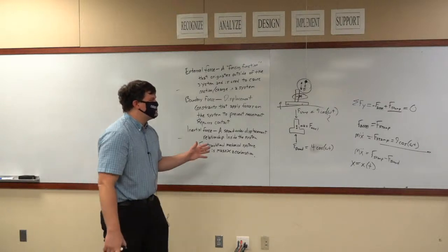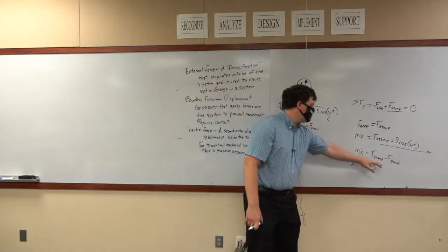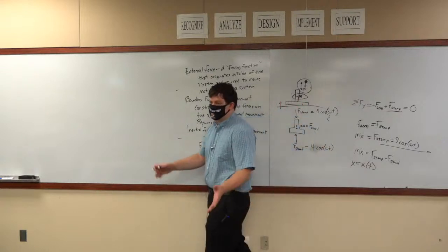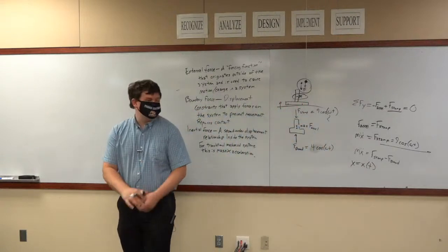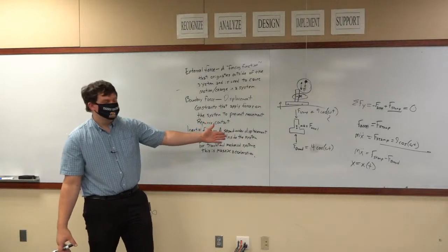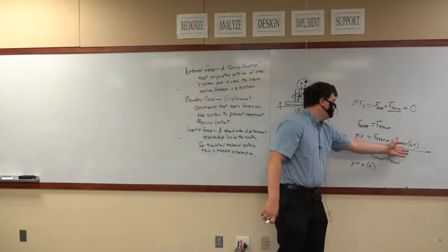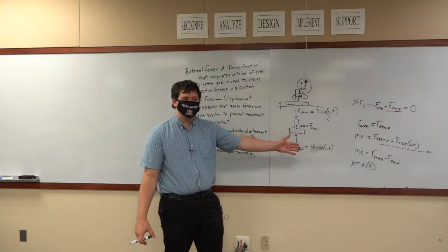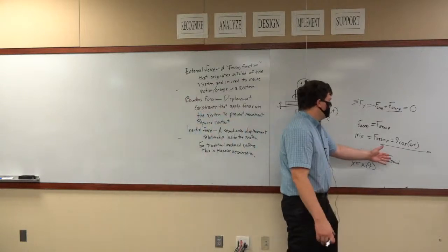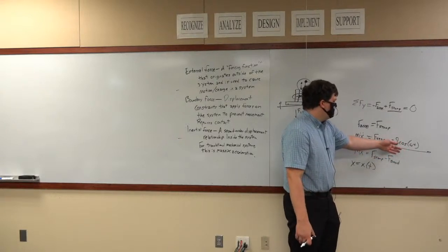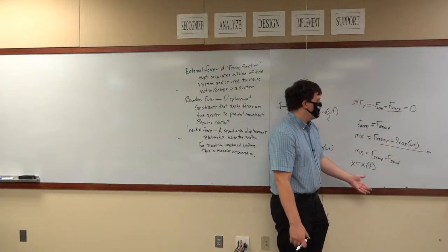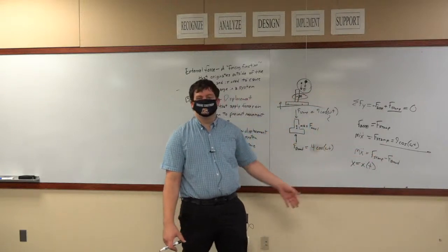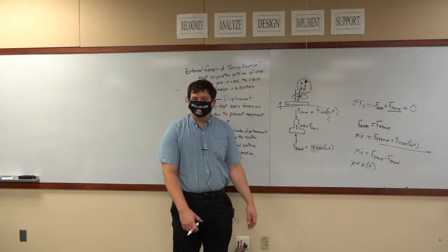So this system itself, pretty simple. If I give you what F stamp is, and I give you what F boundary is, you can solve that no problem. You figure out what the acceleration is. You can probably do 2 integrals over this. Integral over a cosine function produces a sine function. Integral of a sine function is a negative cosine function. So you end up with, what? Negative 9 over omega squared cosine of omega t is your acceleration. There you go. Done.